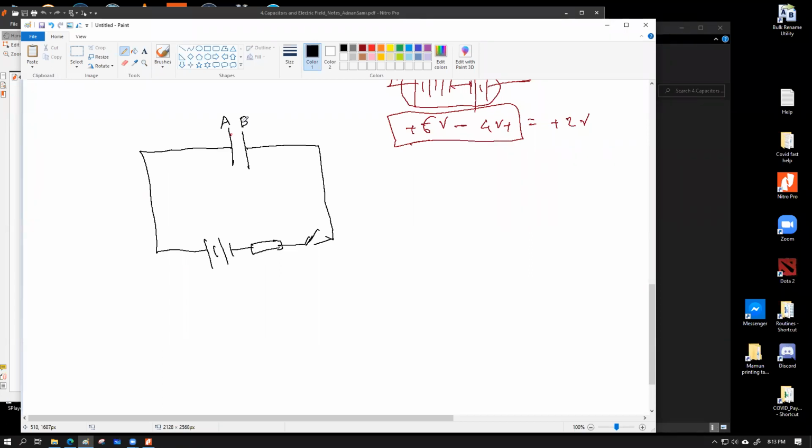Hold up a second. Let's say in this condition, this battery, I assume this battery to be 12 volt, okay? And the moment we're going to close the switch, current is going to start to flow. So initially the voltmeter reading that we had connected across the capacitor was supposed to be 0 volt. As time goes further, this voltmeter reading will increase to how much? The supply voltage that you are feeding this capacitor from is 12 volt.